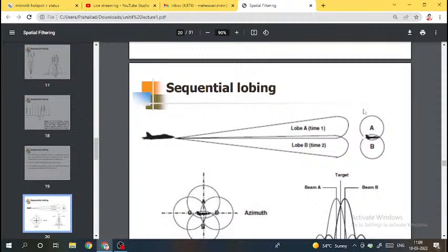The two received signals at the 2 positions will be the same; the amplitude remains the same. But if the target is towards position A, the amplitude of A will be larger compared to B. Using this analysis, you can find in which direction we have to rotate our antenna, right? If the target is aligned along the switching axis, beams A and B will have the same amplitude.